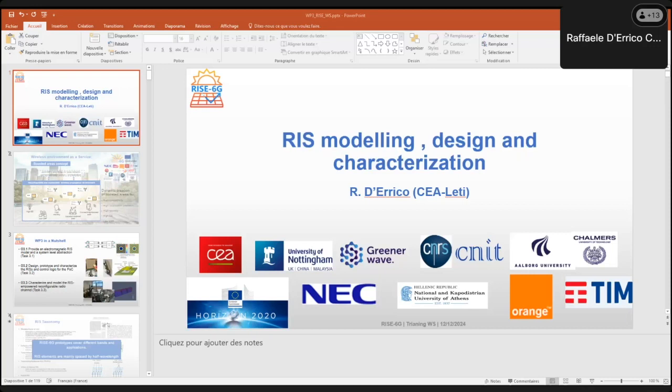What is important is that we extend that to some realistic design. This one, for example, provided from CEA, is quite different from the ideal dipole-like representation of the unit cell of the RIS, because actually we don't have just one port, but two ports with two pin diodes. And here we realize the 1-bit phase shift, which is basically a phase shift between the two states of 180 degrees.